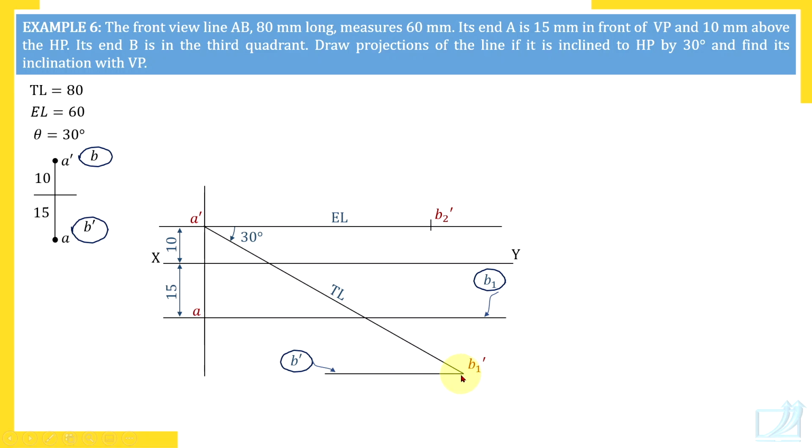So when you draw a vertical line through B1 dash, which other point on that line? Of course B1, front view and top view on same vertical line. So for B1, there is already one more line in our drawing. This is the line on which B1 is. So this is how we have found out B1. So AB1 is PL. Don't use compass right now, because there is one more labeled point through which there is a horizontal line but no vertical line.